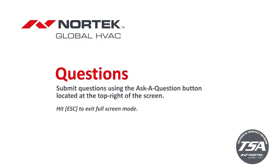The charge calculator is good for either commissioning a system to see where you are and if you need to add any additional charge per your system matchup. It's also good to get a straight baseline if you come up on a system and you're not sure where you are currently, and you want to run those numbers through the charge calculator. It's a good starting point to see where you're at charge-wise on a system. So good question.